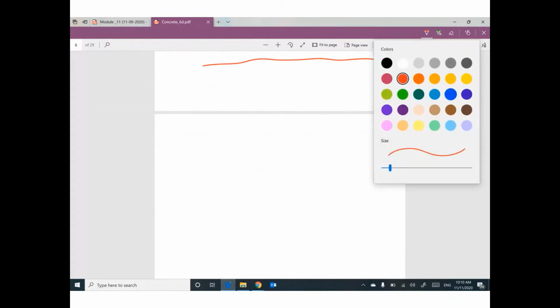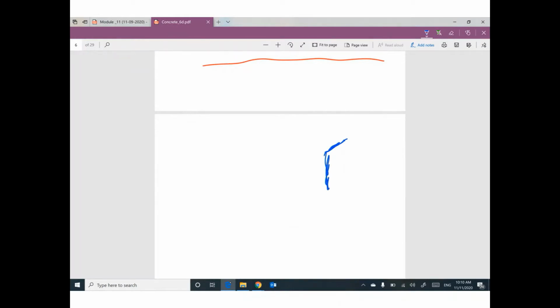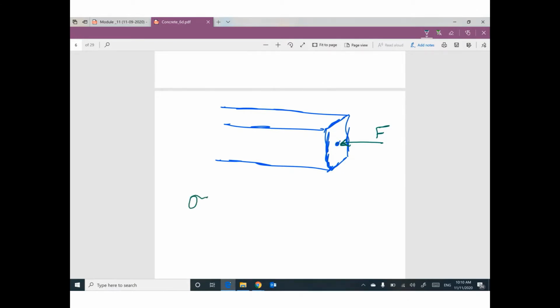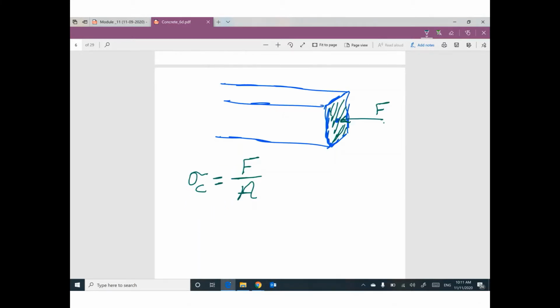We learned also, if you have a beam and this beam has a centroid, and we have compressive force F at this centroid, we can expect stress called sigma equal this force divide area. Do you remember that? If you have axial force on a cross section, we have compressive stress. This one will be compressive, equal this force divide this area. And the distribution of this stress will be uniform. Compression, compression, how much? Force divide area.